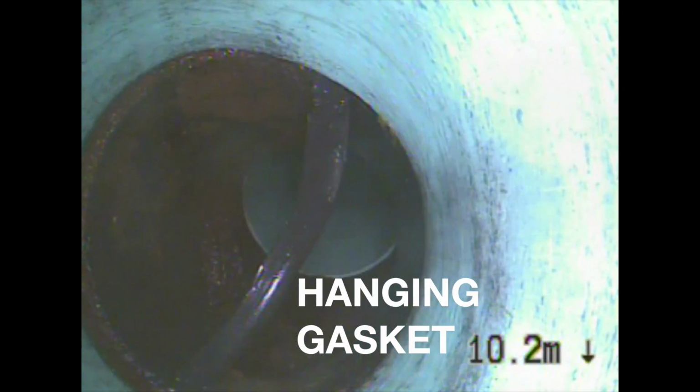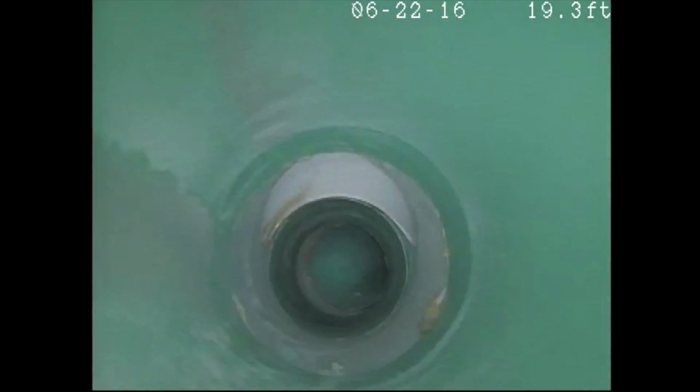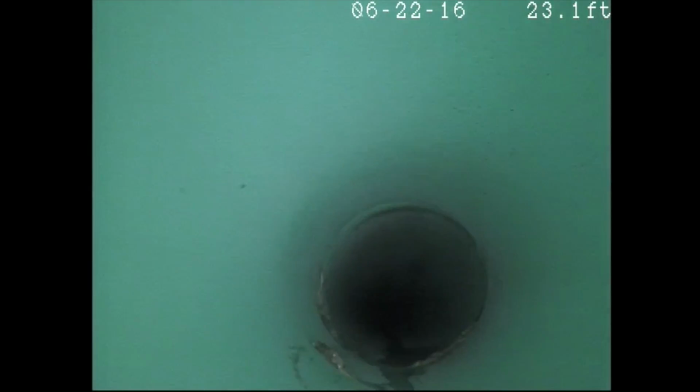Furthermore, the camera has the ability to locate potential problems. A hanging gasket, leaking fittings, debris buildup due to pipe settlement. It is this ability to instantly identify problems that illustrates the benefits of on-site camera inspections. Whether it's the camera test or the ball test, both are reliable ways to confirm the job was done right.